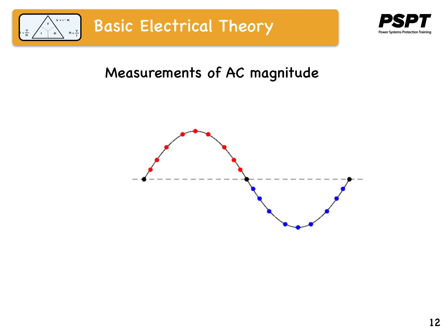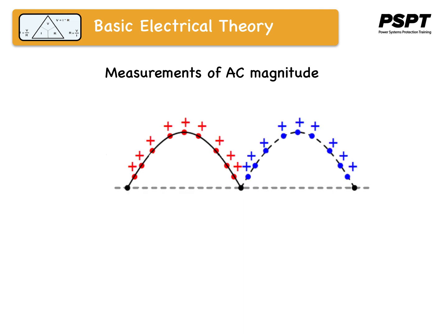If we average all the points on the waveform algebraically, that is to consider their sign either positive or negative, the average value for most waveforms is technically 0, because all the positive points cancel out all of the negative points over a full cycle. However, as a practical measure of a waveform's aggregate value, average is usually defined as a mathematical mean of all the points' absolute values over a cycle.